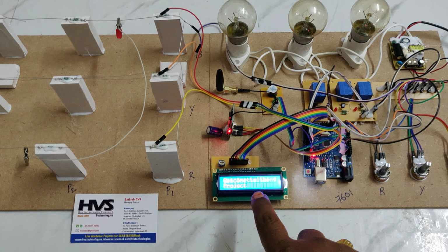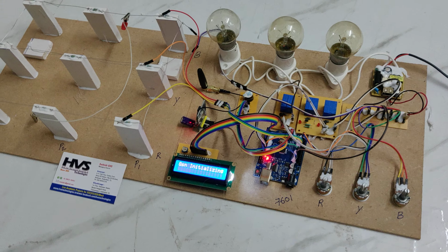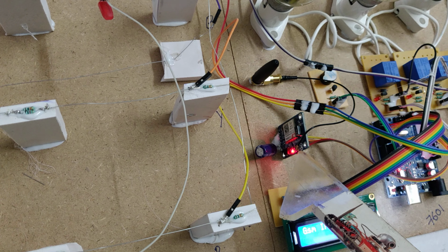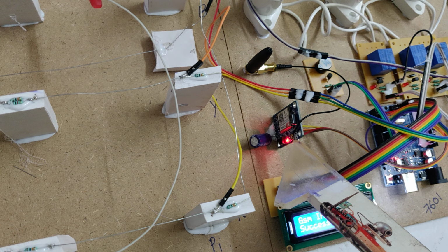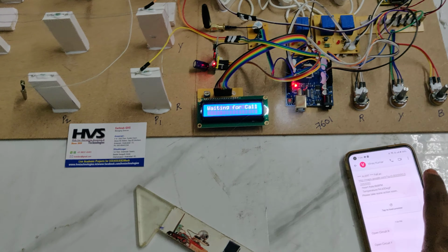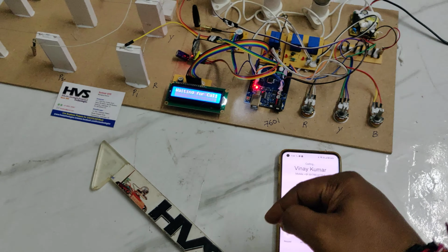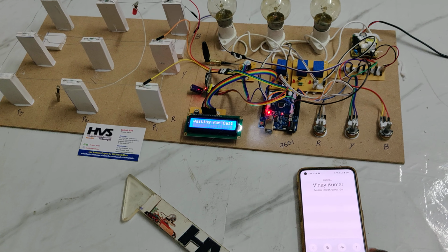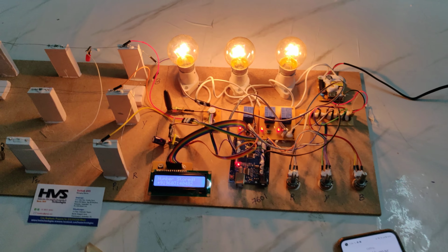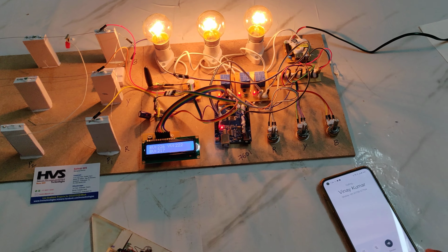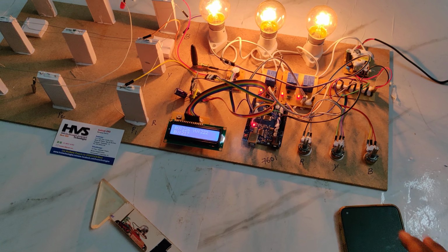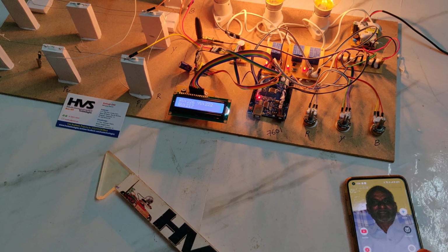Initially a welcome message is displayed and the GSM modem gets initialized, and here you can see the light blinks very fast initially. Once it gets the signal, the blinking rate slows down. Right, now you can see that it has slowed down. So now it is waiting for the call. Then make a call to the SIM card inserted into the GSM module. Right, my number got stored, and until we switch off the kit, my number is the authorization number, so my number will receive the messages whenever an abnormality is detected.